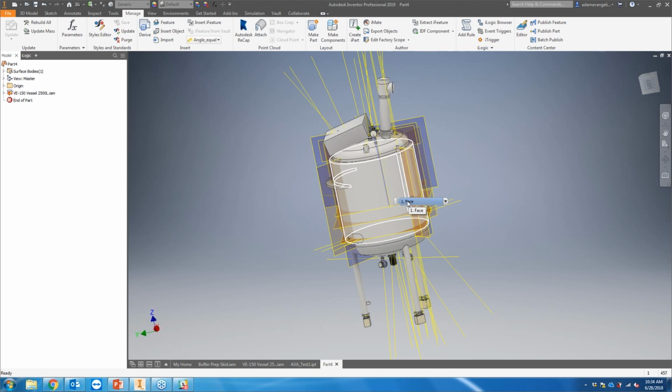When you're looking at the copy design functionality in Vault, you want to carry over the entire assembly structure, but maybe replace a few components. In this case, we took an entire assembly and we got considerably more options when we were doing the simplification, and we generated a completely separate part from it, as opposed to having that same assembly and replacing some of the components.